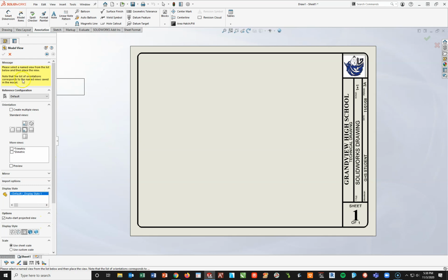Specifically, what we need to do is, one, make sure that our view, and here are our views, I can do a front, I can do a bottom, I can do a top, I can do a right side, I can do a left side, and I can do the back. Okay, unfolding the box. What I want to make sure is when we start our drawings, we should always be starting from the front view. That's the center box right here, front view.